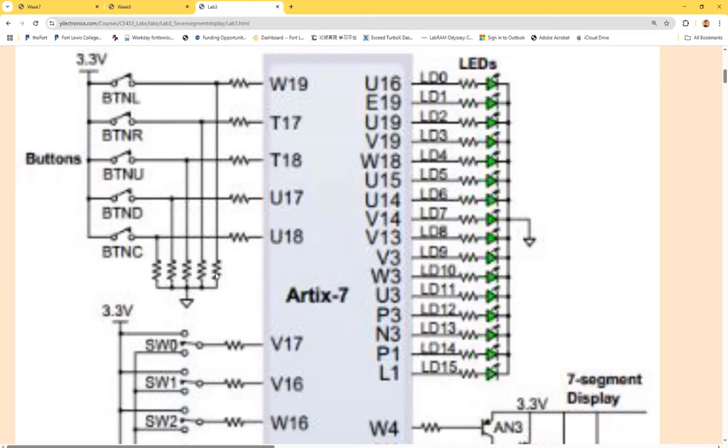So it's getting put down to 0, right? These are pull down resistors, keep in mind. So they are getting put down to 0 at the very beginning. So basically these pins are getting zeros. And you press it, this pin here is being put up to VDD or shorted to VDD. So it's a rising edge or falling edge?